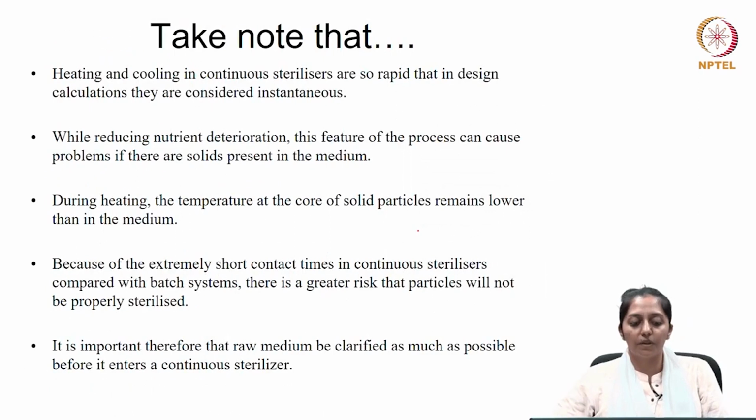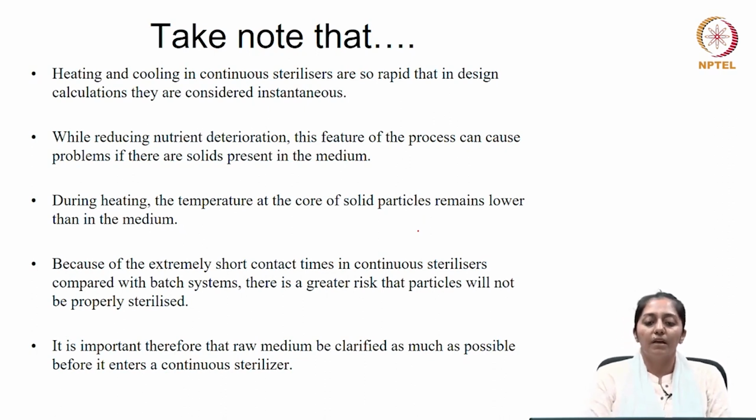So, what is to be noted here is that heating and cooling in continuous sterilizers are so rapid that in design calculations they are considered instantaneous. So, while reducing nutrient deterioration, this feature of the process can cause problems if there are solids present in the medium.